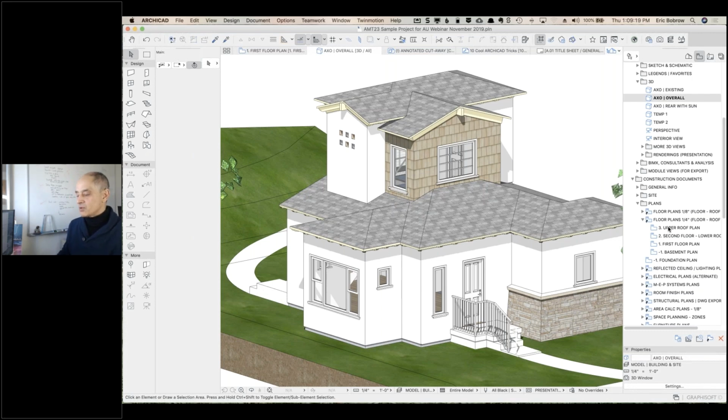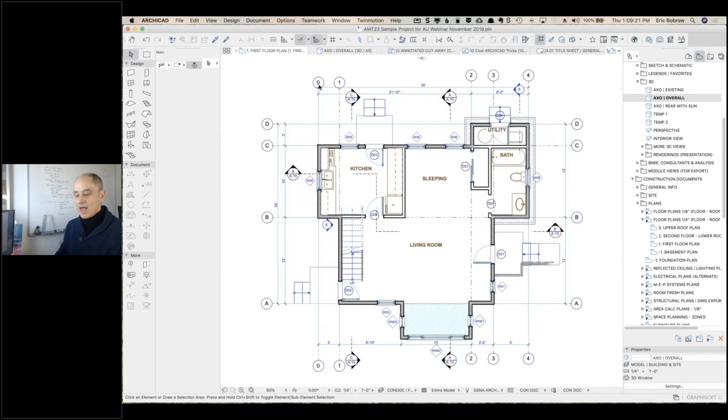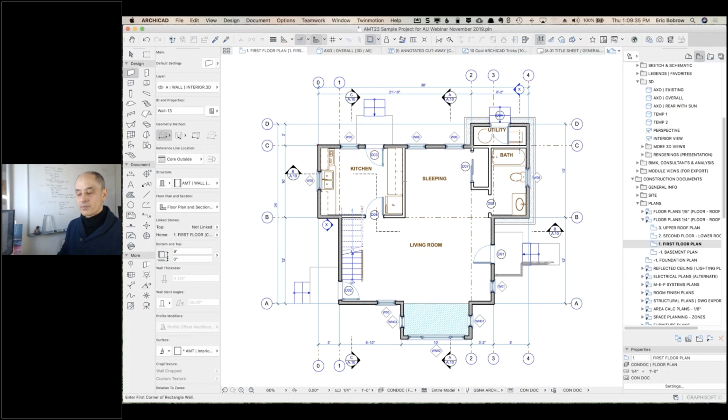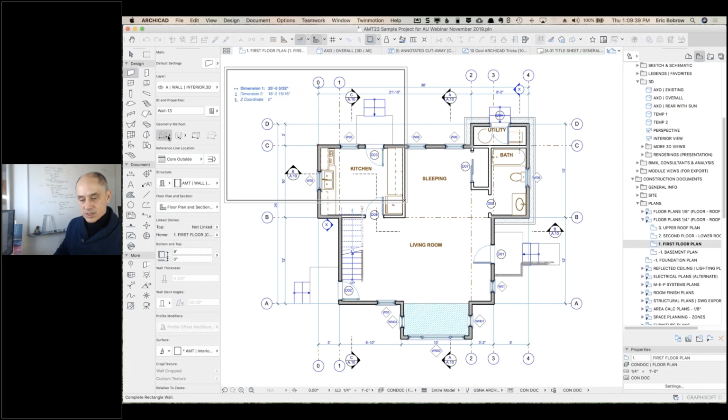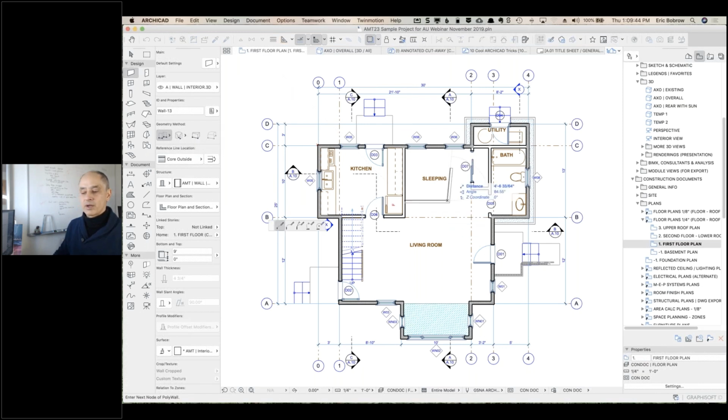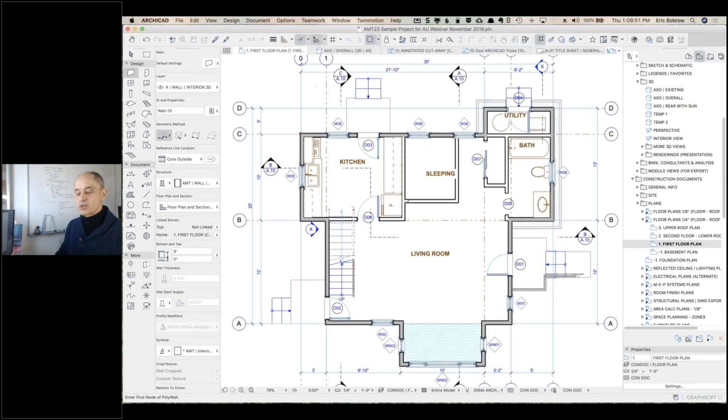Now, if I go back to the plan here, and you should all know that you can use the eyedropper either by clicking on this icon or using the shortcut key, the Option or the Alt key. And you say, I want to do another interior wall. Hover over an interior wall like this, and then you can go and, particularly if we have this set for just a single wall or a chain of walls, we can draw another wall and another wall. Now this is going to go into the window, probably not a good idea, but basically we picked up those settings. So that's the eyedropper.